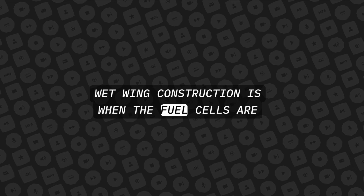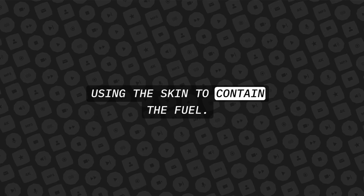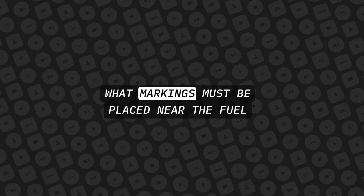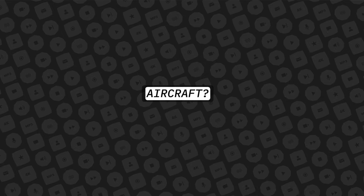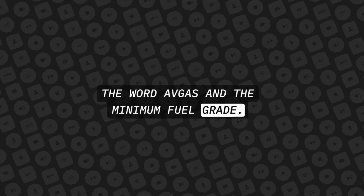What is wet wing construction? Wet wing construction is when the fuel cells are built into the wings of the aircraft structure using the skin to contain the fuel. They are known as integral fuel cells. What markings must be placed near the fuel filler opening on reciprocating engine aircraft? The word avgas and the minimum fuel grade.